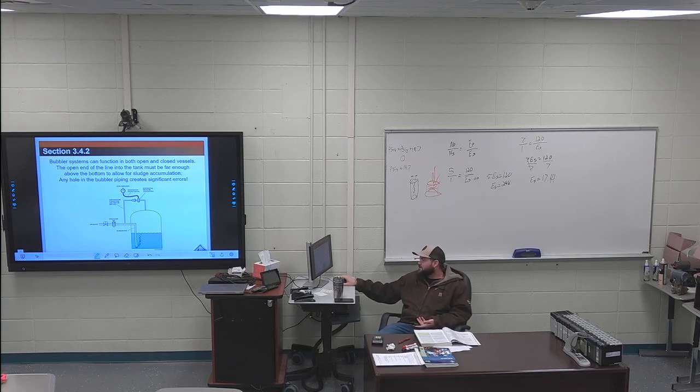So based on the amount of back pressure that's put on this bubbler system, they can determine a height. Does that make sense? So this is good for areas like, we used one of these. They were about to install one in a big tank that was very volatile. The pipe to the tank was a few feet up to fill the tank, so when it was pouring in there, the top level of the tank was moving all around. We had floats in there, just tied floats to the side. Those floats are constantly turning on and off, stuff like that.